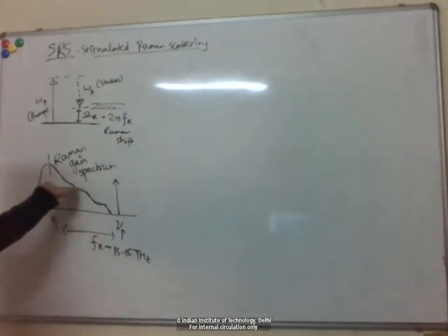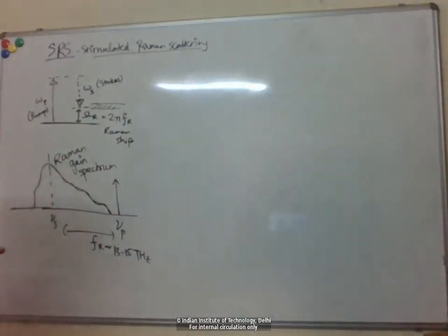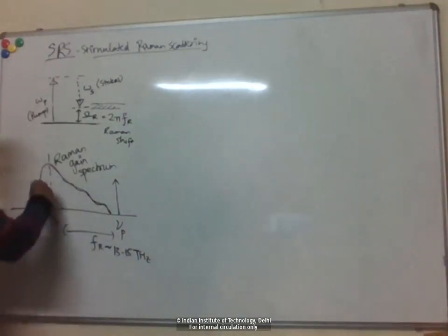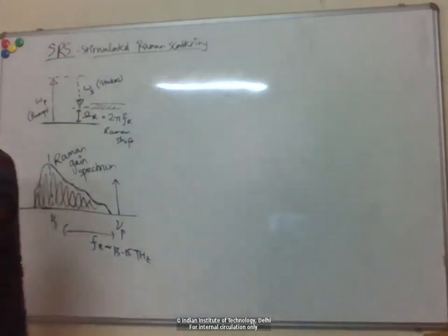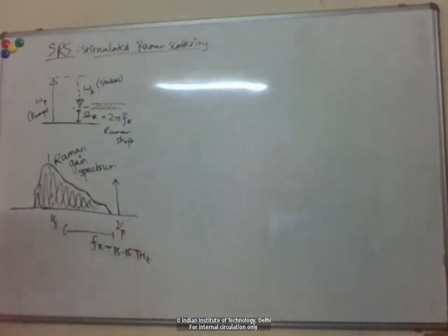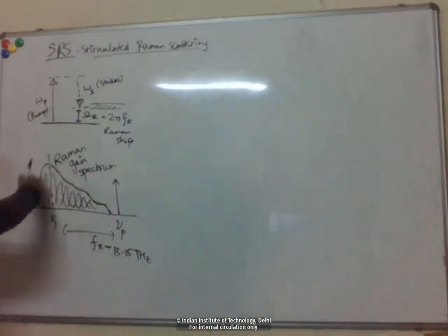And this is basically some sort of inhomogeneous broadening. Basically, now you have not a particular crystalline structure, but again, you could have different SiO bonds with some dangling bonds lying around. So you can imagine that there are many different narrow gain spectra, which are all shifted from each other depending on the local environment around each place. And then when you add all of them up, you get this broad spectrum. Okay.